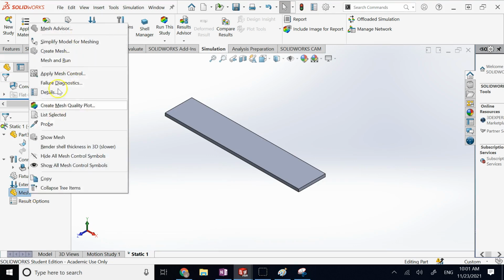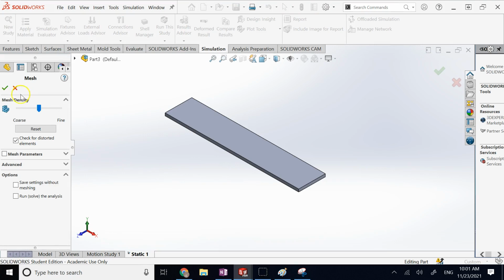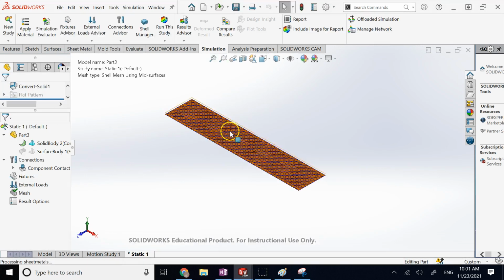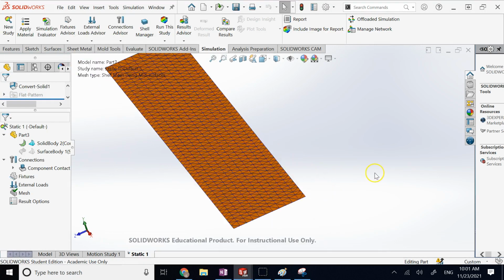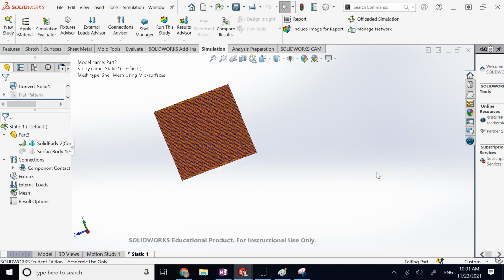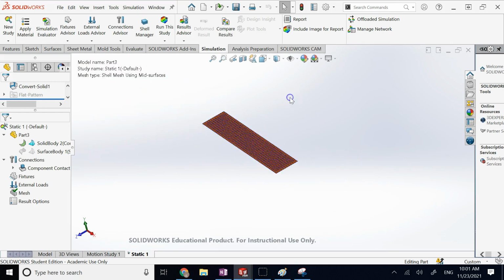I used edit definition, and then I create a mesh, and look again. You see, this is again that 0 thickness shell. So you can create a shell either manually or by edit definition. Manually from solid models, and by edit definition through surface and sheet metal. So this is how to create a shell.